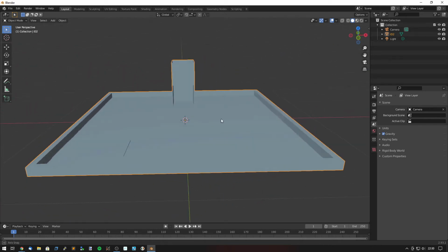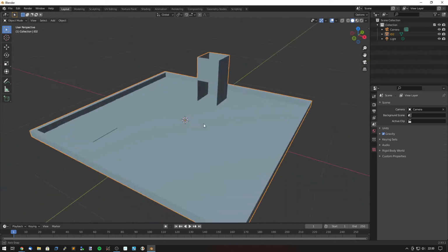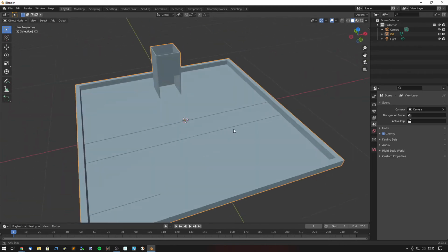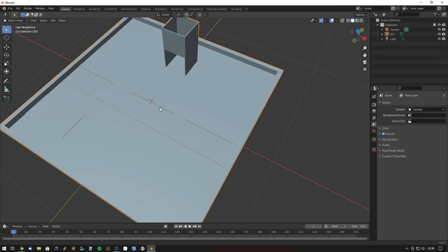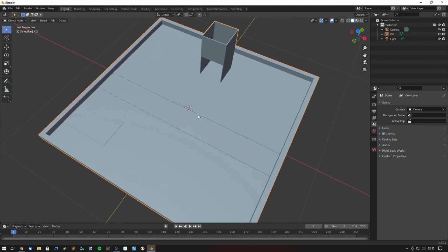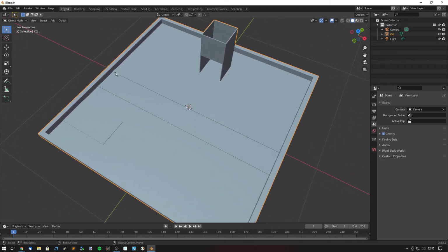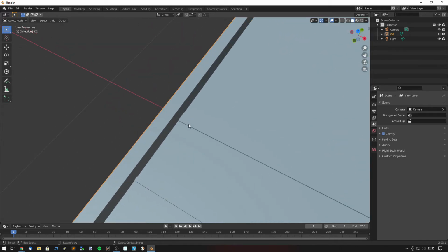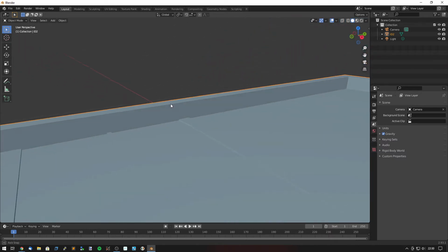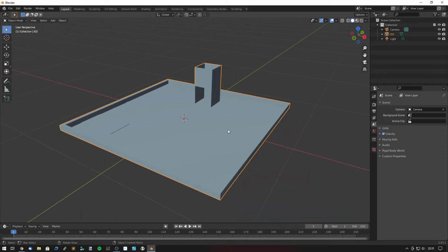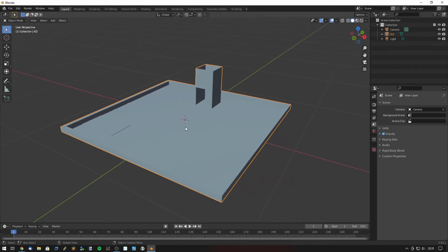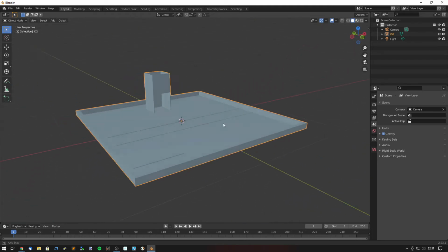Okay, so we can then see this has been brought in and it will be to scale. And we can see here using the middle mouse button, if I click and hold the middle mouse button, I can rotate around and orbit around the center point here. If I want to move the center point, you hold the left shift key down, and the middle mouse button clicks will then move you around rather than rotate you. If I want to recenter the view, I move the mouse where I want to recenter, hold the left alt and then click on that one and it'll center it. And I can zoom in, rotate around that object, zoom back out, center it again. So left alt, click and then let go. And then shift to pan, and just the middle mouse button, it'll rotate.